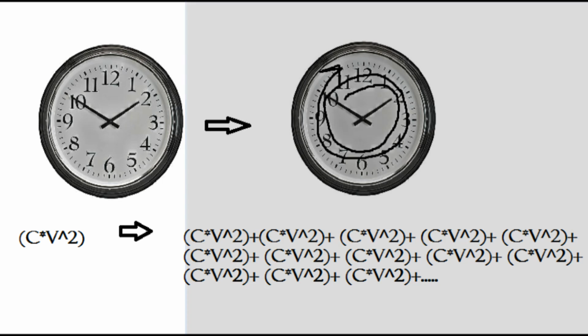So let's take a real quick look at how clock frequency and power consumption are related. We're often interested in getting a higher cycle count per second. So if our clock ticks faster, assuming other things being equal, we're getting more done. This comes at a cost though, and not just in terms of design trade-offs. We can look back at our equation and see that if we increase the frequency at which we flip a transistor, it's going to consume more power.